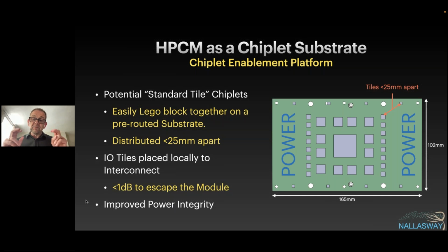But this is at the pluggable level. One of the big challenges of chiplets is we've all got to spend $1 million putting a bunch of chiplets on the same substrate. Whereas if you could make some of these chiplets pluggable, maybe with a picojoule per bit or 1.5 or whatever, then suddenly it allows me as a systems engineer, as a one-man band wanting to build a special purpose computer, to just buy the bits, buy the active cables maybe with the chiplets in them, and plug it together very quickly and very cheaply without spending $1 million on my preferred packaged set of chiplets. And so that's the sort of top-down thinking that I'm trying to do here.